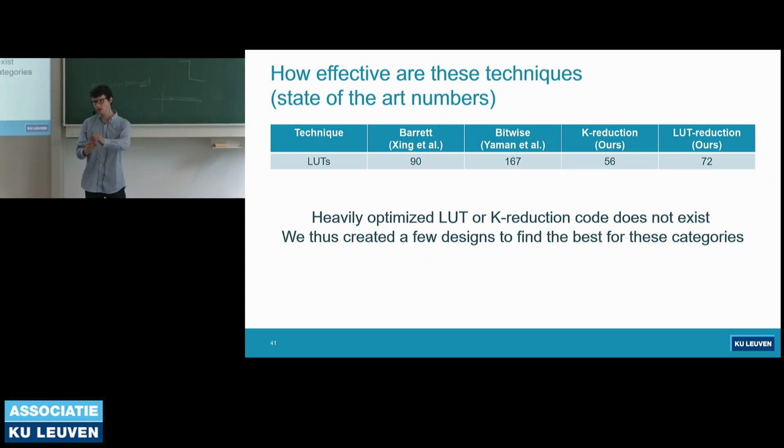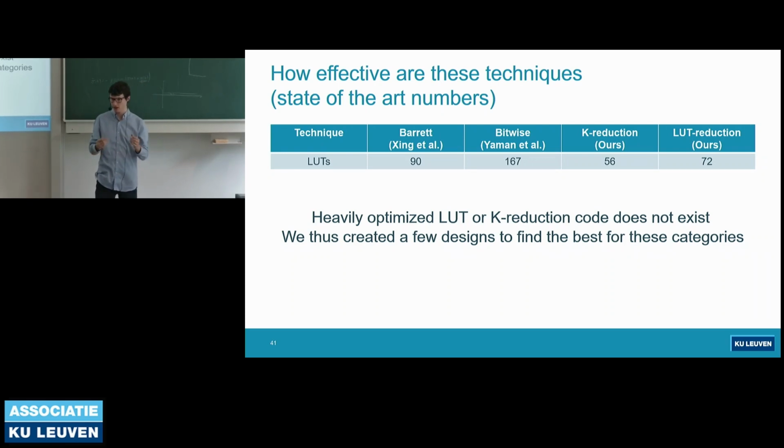And your K-reduction went from 24 bits to something that is 16 bits. So neither of these things fully reduces the thing. You have to apply it multiple times for it to work. So one thing that you can do is first do a LUT reduction and then do a K reduction, because each of them has different advantages and disadvantages going towards the very end where you have to do conditional subtractions.